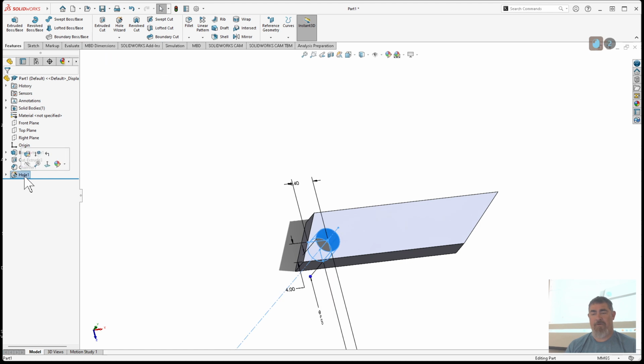But I could just click on it and say 5mm. And rename my step. You can do the same thing in Fusion. Just in Fusion, there are just the icons down there. But as you roll over, you can see what you've renamed. I almost never rename things in Fusion, but here I might rename more often because now I actually see what it is.